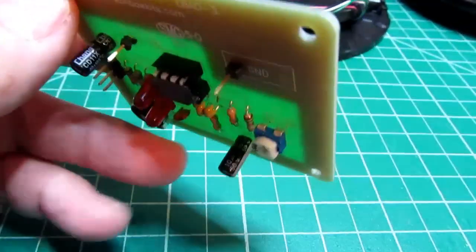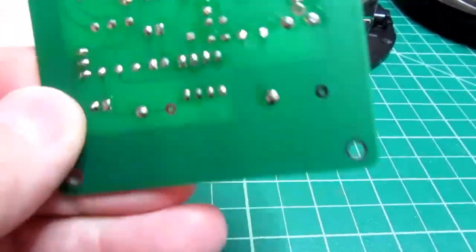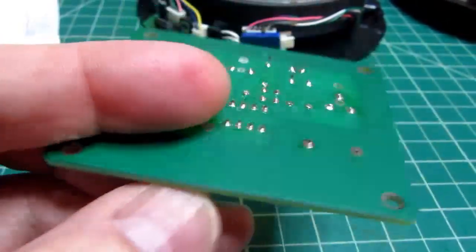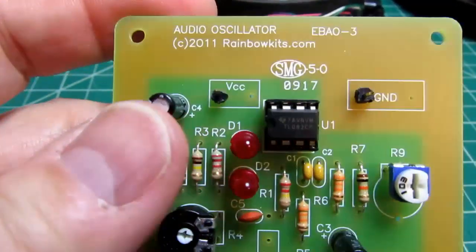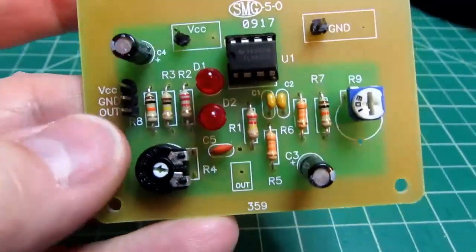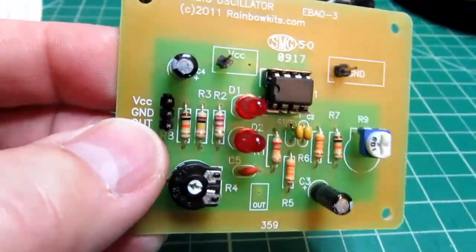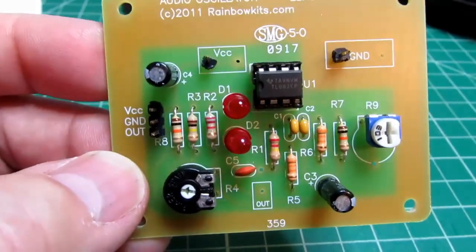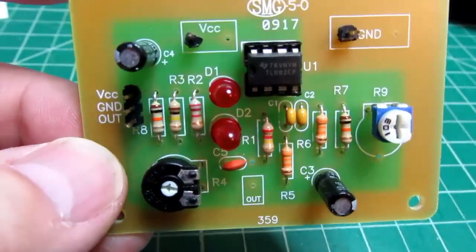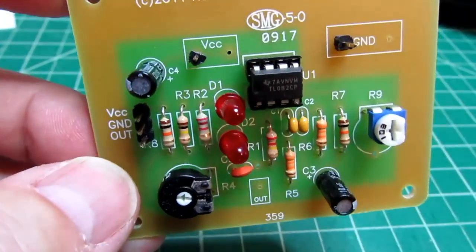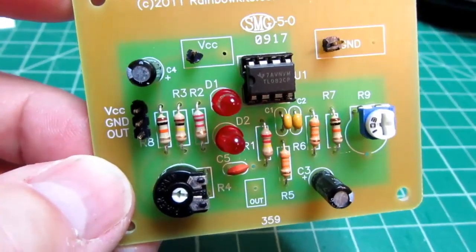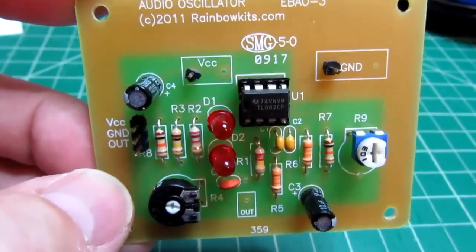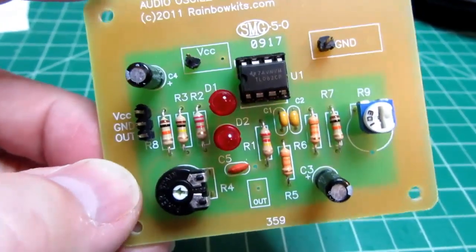There were some things I wouldn't have done, like this is a dual op amp, and the other op amp in the package isn't terminated in any way, it's just left floating. It's not the end of the world, but I would say that good practice is to do something with those inputs. It doesn't overheat or anything, but still. It seems like there's a disconnect between the documentation and the parts provided.